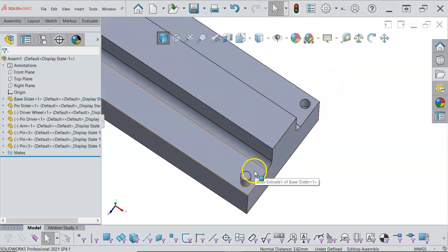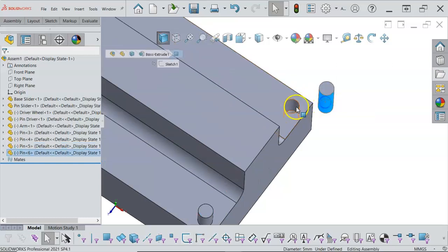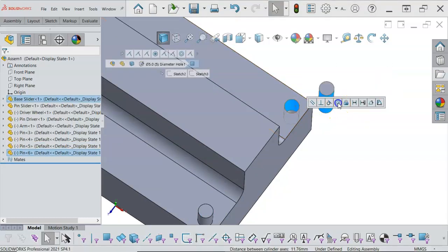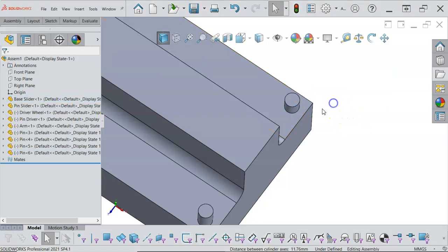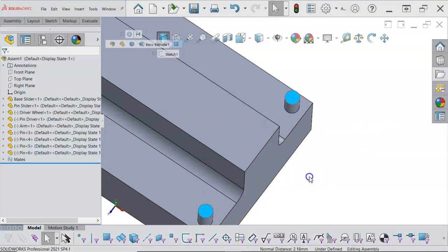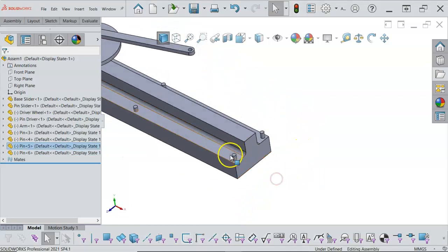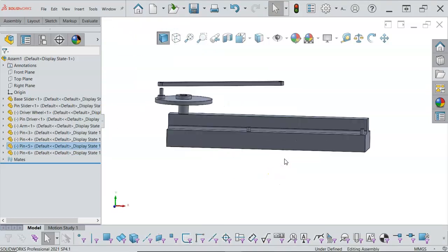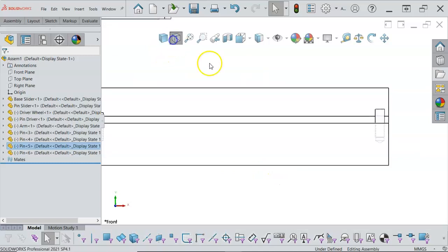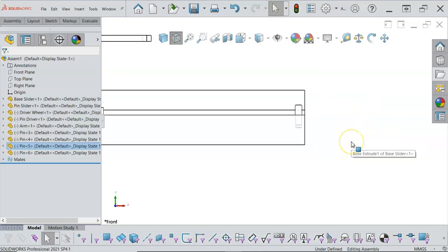All right, and then from the work area, if I hold down the control and grab, which is why you want to be careful with some of the selections, then we'll go concentric, and maybe I'll go coincident to the faces. That was a weird little jump, but I'll go coincident to the faces. So if I want to change the depth, we go to the front view and look at it with hidden lines, and maybe I wanted that seated. I got a couple extra millimeters there.